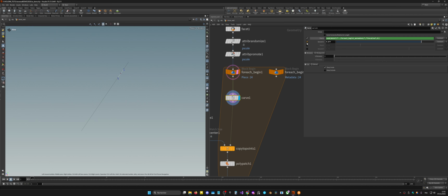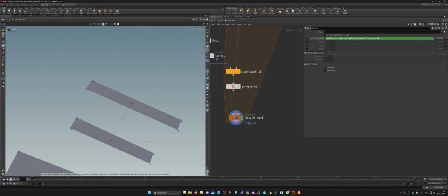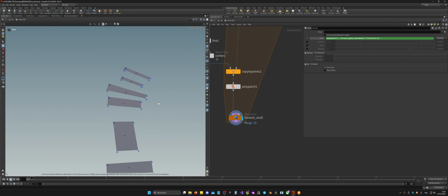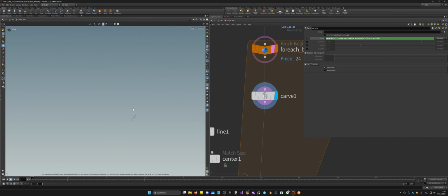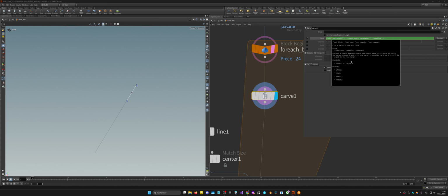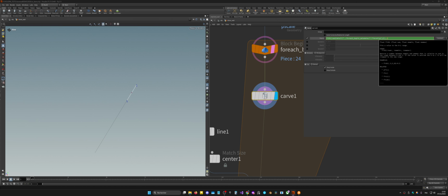But let's uncheck the first one. So as you can see, maybe the cuts are very different for each. You see the size is very different. Okay. So I don't want it to be cut like this. It's a huge cut. I want a very limited part of this random. So I will use fit01. That will remap the value of the random from 0.1 to 0.35 maybe.